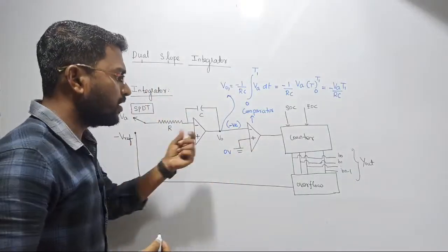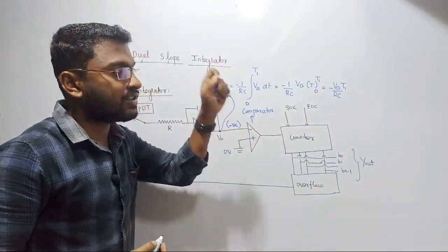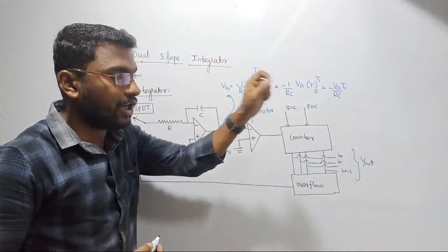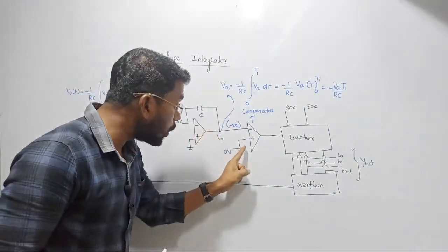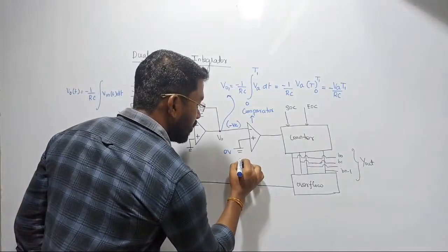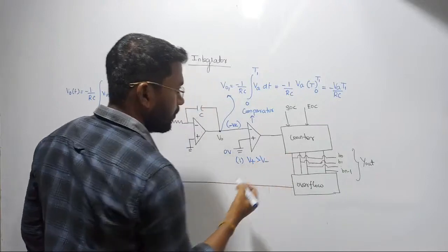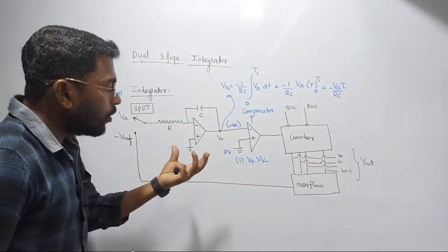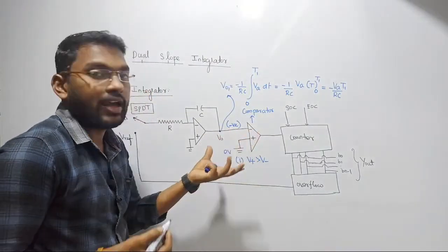Of course. And the next statement I would like to conclude here. We all know 0 is always greater than negative voltages. Yes or no? Yes. You can keep any negative voltage here, but 0 is greater than negative voltage. It means I can say case number 1. In case number 1, V plus is greater than V minus, because the available voltage across the non-inverting terminal is 0, whereas in the inverting terminal I have negative voltage.